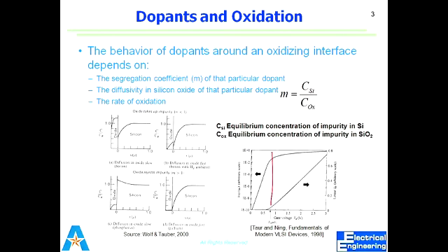If you are still confused, let's suppose I have silicon that is 1 micrometer cube. It's too much actually, that volume is too much. I should say it's 1 nanometer cube. And silicon dioxide, as I told you, when this silicon is consumed, how much silicon dioxide should be produced? 2 times. 2 nanometer cubes. So when this silicon is consumed, this silicon dioxide is produced.